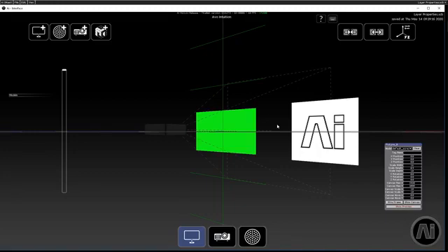You can, in your self-build, use GeForces, NVIDIA's. They will come a little bit better for some of the shader code stuff, but do not try and use two GeForces together in a machine, because the way that their SLI works is counterproductive for our software and will actually reduce performance.